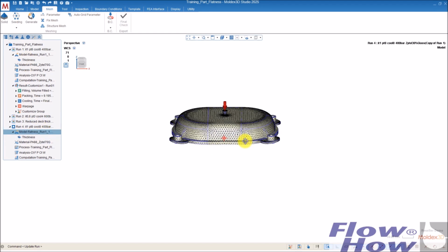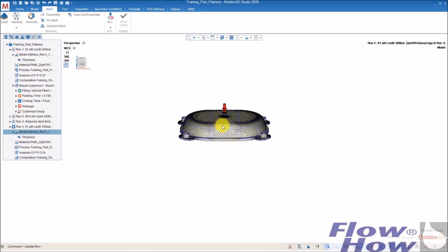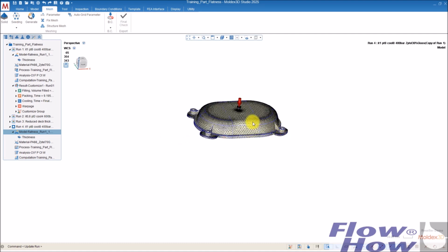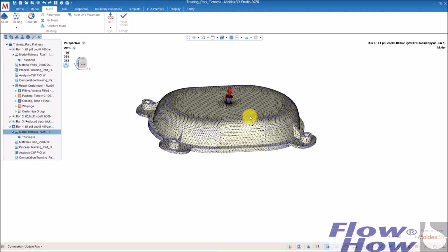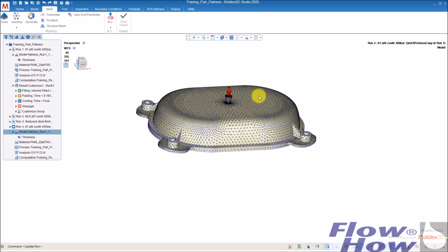When I want to change anything, I normally start wiping off all solid mesh, so I only have the geometries and the surface mesh. The solid mesh is just a push on the button and a small waiting time. So the surface mesh is the problem, and also the model.